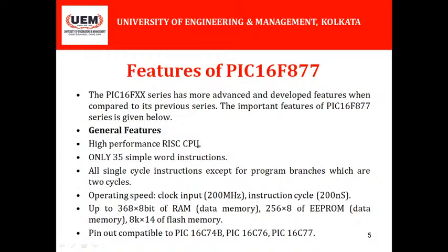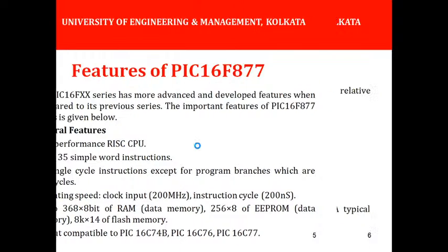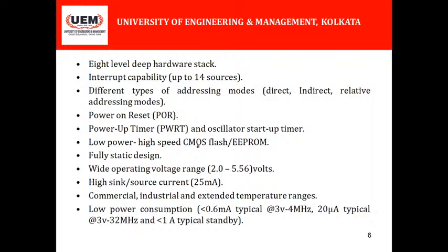So these are various versions of this microcontroller series. Next general feature is 8-level deep hardware stack, interrupt capability. There are 14 sources from which an interrupt can come.